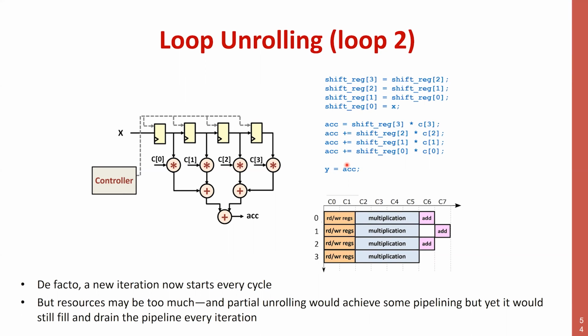The only thing that I can do is, again, the same trick that we played before in part 1, where we have restructured our sequence of additions. There are 3 additions here to be done, and we can create a binary tree, which doesn't seem to be too different, of course, because it's a small number, but here it is the binary tree of additions, where we do at least 2 of the additions in parallel. So from 3 cycles for the 3 additions, now it goes down to 2 cycles for the 3 additions.